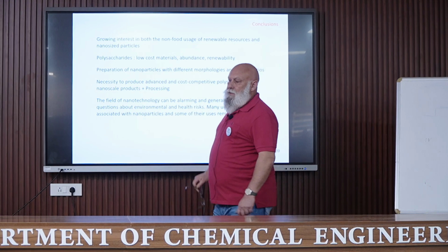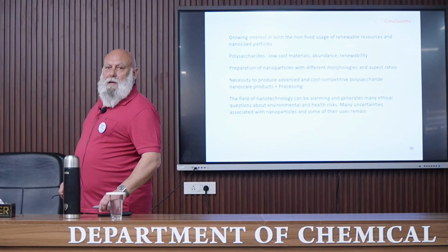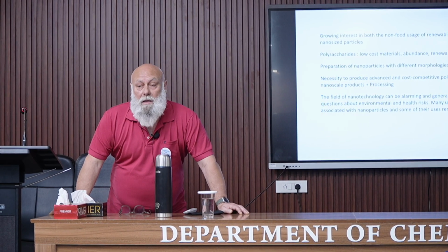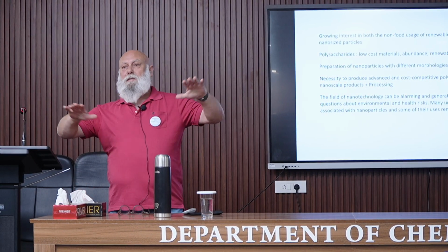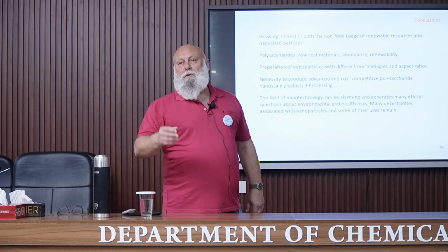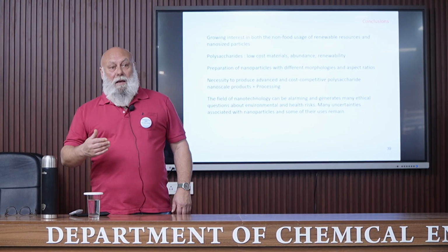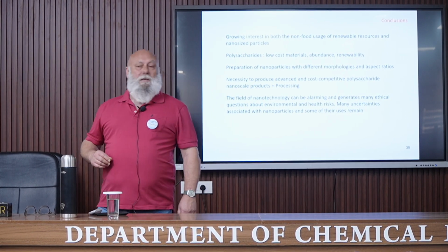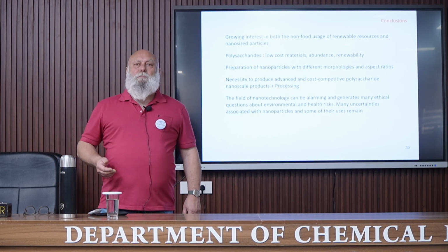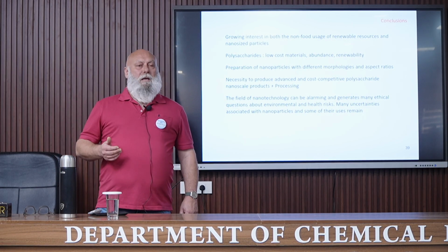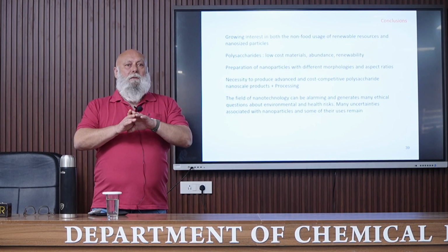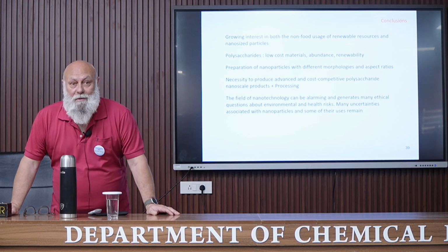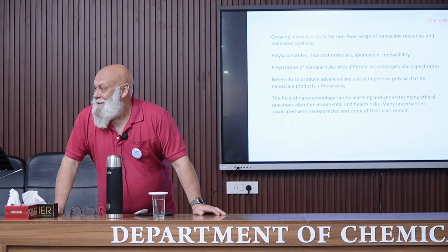But you have to remember that if I take as an example cellulose nanocrystals or cellulose nanofibrils, they are obtained in an aqueous dispersion. And so they are well dispersed in water because of residual hemicellulose on the surface in the case of nanofibrils, and because of sulfate groups in the case of cellulose nanocrystals. Now, when drying this suspension, it's no more in the nanoscale because the nanoparticles aggregate, meaning that the risk is probably limited.